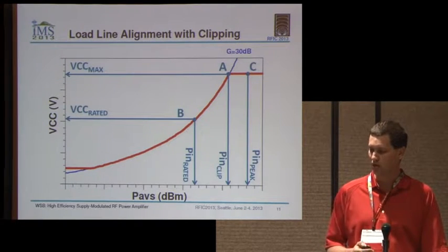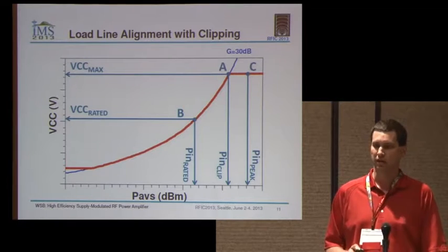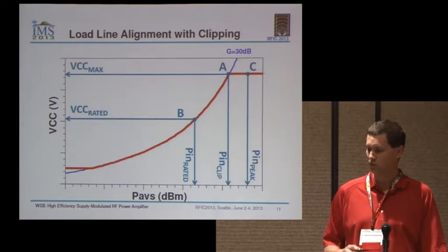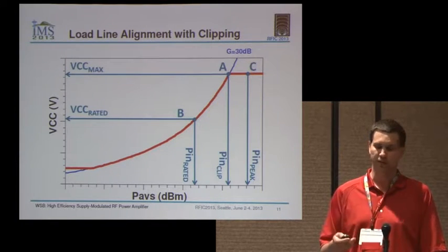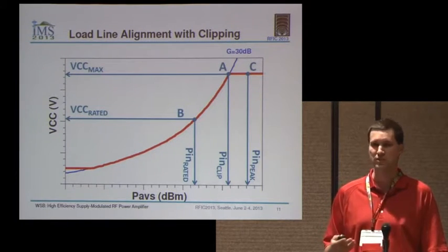That's going to move our VCC rated up higher. And the bottom line is it's going to end up allowing us to use a higher load line for the PA, and the advantage of a higher load line is higher efficiency in the PA.